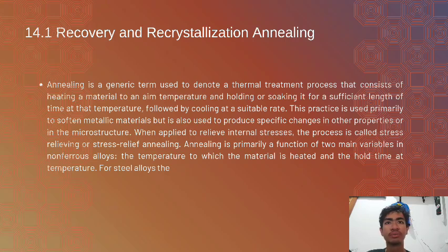When annealing is performed for a short period of time or at low temperature, the hardness of cold worked alloy remains relatively constant. This is true because the level of temperature activation is not sufficient to significantly affect hardness during recovery.